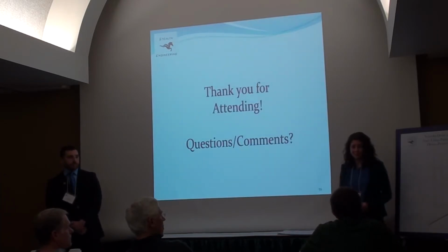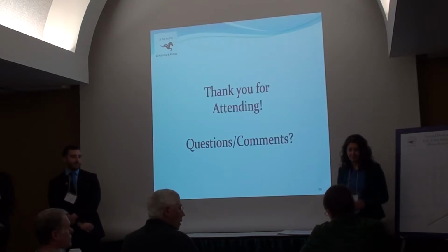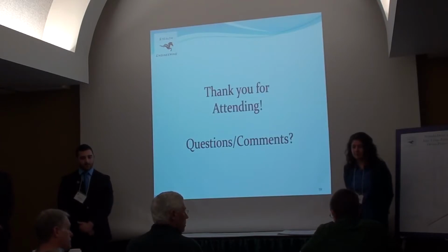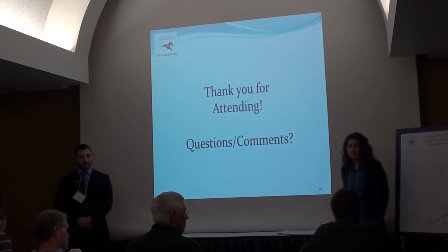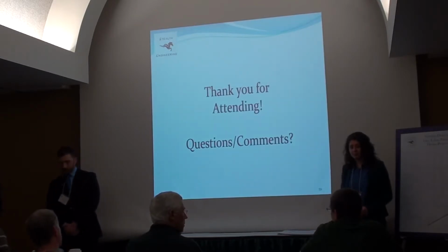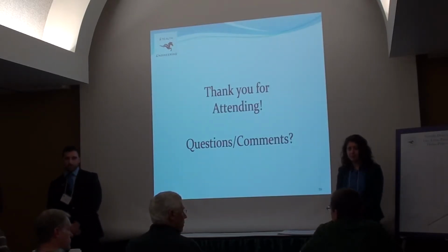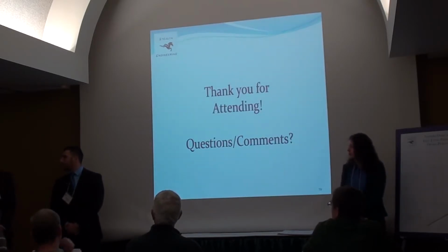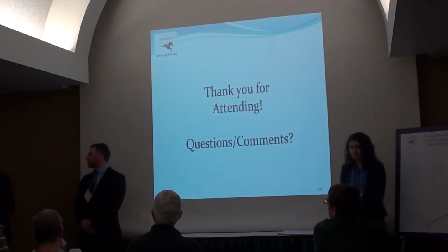I'm Tyler Dawson, MTH Consultants, and I'll ask some questions here, mostly on the pavement. We'll start with your outlet for the retention pond goes under Marsh Road. Did you consider horizontal directional drilling or a trenchless method to install that instead of having to close Marsh Road? Yes, we did. Speaking with the hydrology specialist, we felt that the drilling would be feasible. It would be easier just to remove the pavement on Marsh Road and just lay the pipe underneath it.